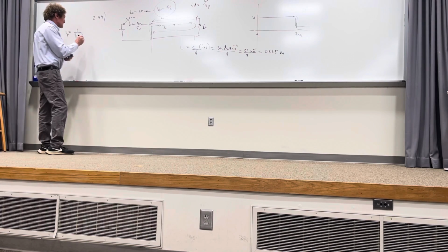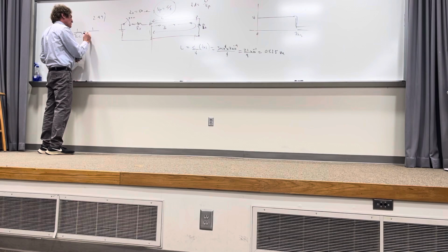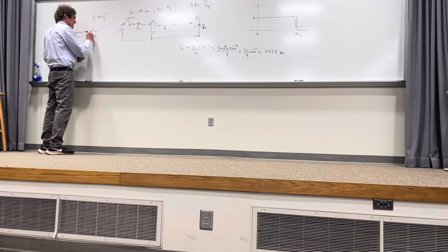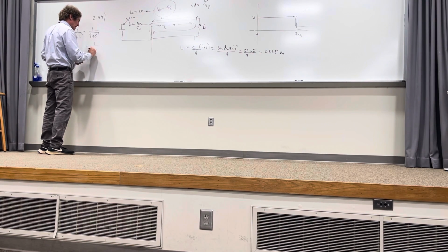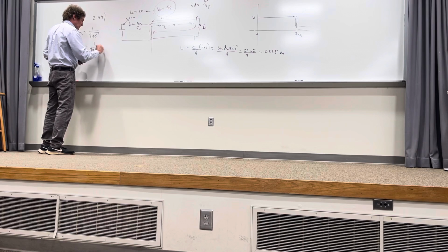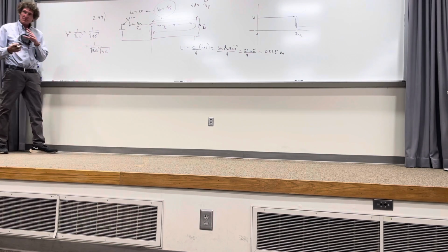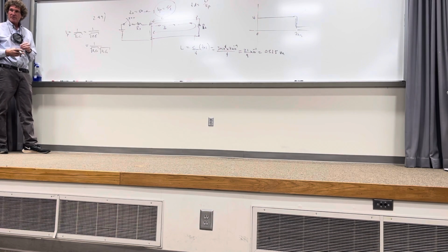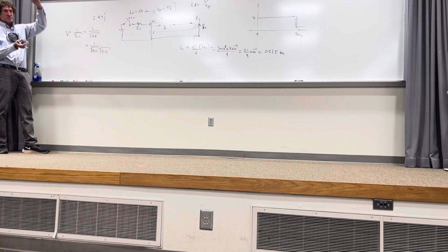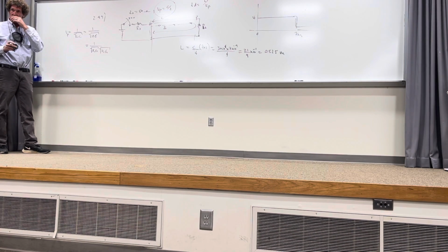So therefore, this is really equal to 1 over the square root of mu in the dielectric, epsilon in the dielectric. Well, that's 1 over the square root of mu naught epsilon naught times the square root of mu relative epsilon relative. This would be in the dielectric of the transmission line, because that's where the wave is manifest. The voltage occurs between the outer shield and the inner core, and it's the wave that's propagating downward.